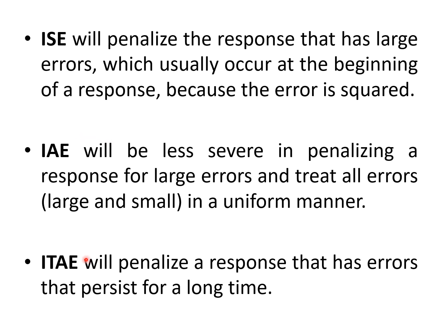And for errors that persist for a long time, you can use the ITAE method. But using the computer program, you can calculate all three methods in one go, and then decide what is the best, smallest error that you will get to decide your controller and tuning, and use this also as a way to tune your controllers and get your criteria fulfilled.